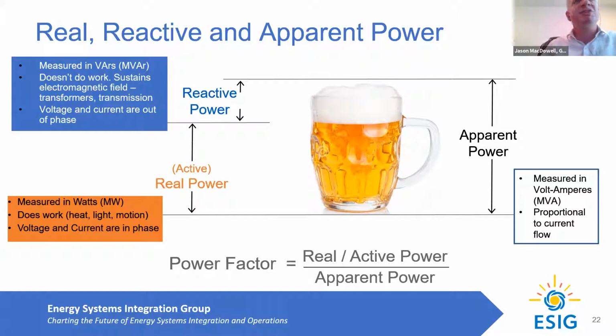So this notion of reactive power may be a little bit more obtuse for many folks, but think of it this way, that in order to have real power being transferred across the network, you need to have a certain amount of support to keep the voltage healthy in order to deliver that power across the network. And that fundamentally is the role of reactive power.